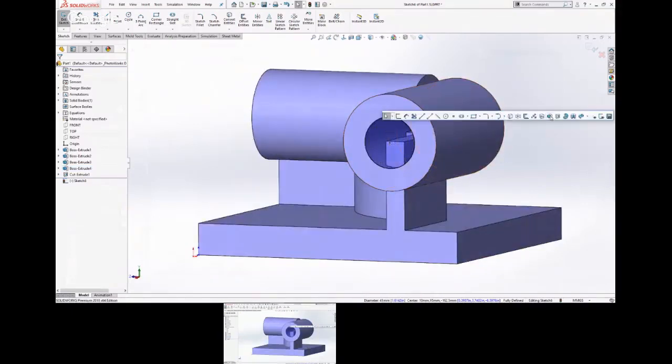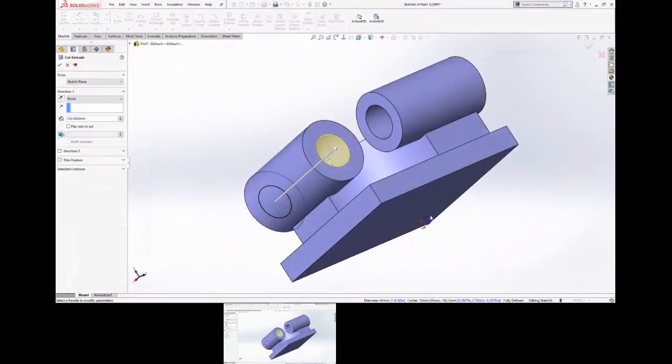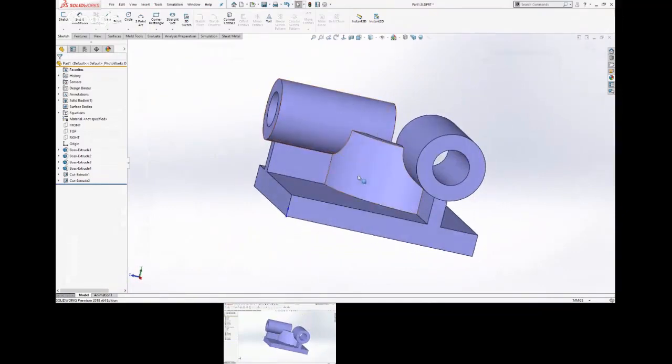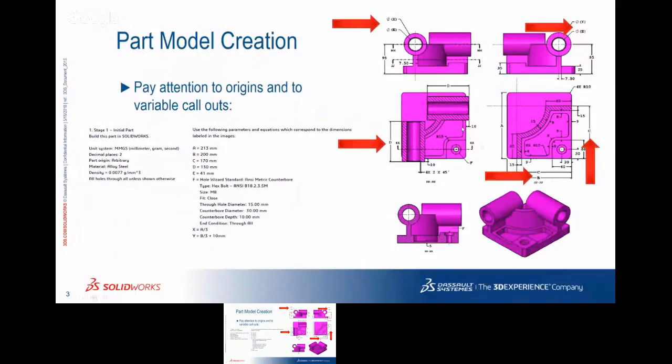The one thing is I have my option to rotate the part to the feature, and that kind of bugs me. But at that point, I've cut them away, and that's quick and dirty. I actually tried modeling these first and extruding this up, but it just seemed to me this is the most straightforward way. Okay, so that gives us our two bosses. So let's go back and look at our part. The next thing we're going to do is this little boss right here.